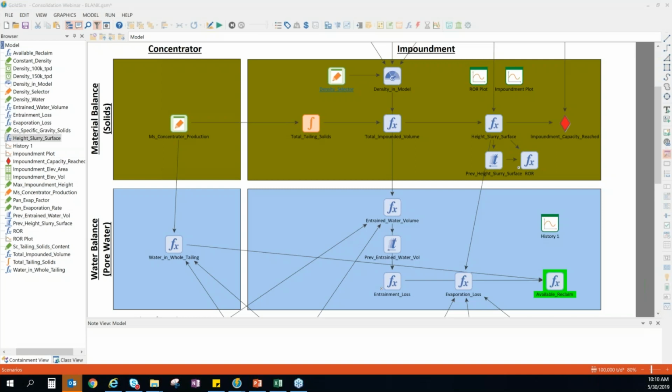But again, the short answer is typically yes. These predictions tend to line up well enough to use for an initial prediction. Again, as you say here as well, calibration of this model is essential. Comparison of actual measured densities to what you assumed for design, that is essential, because there's always a limitation on what we can do ahead of time to try and predict the behavior of these materials.